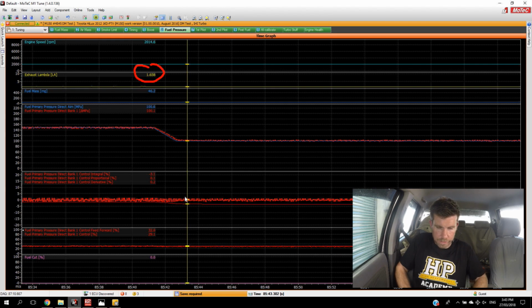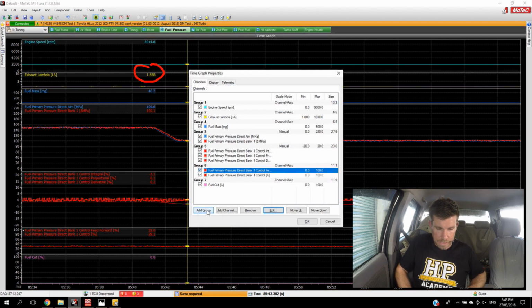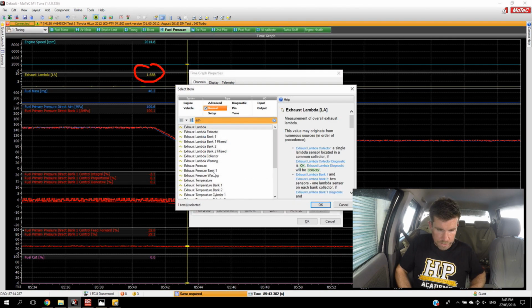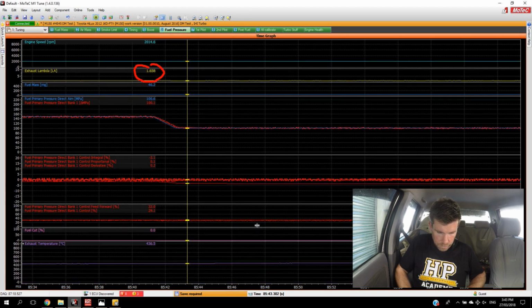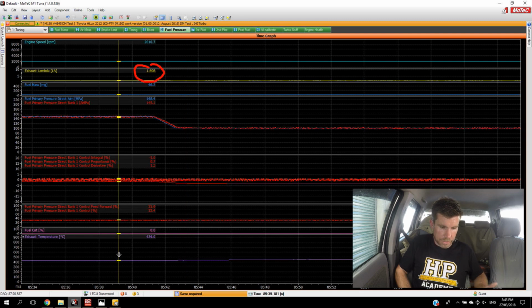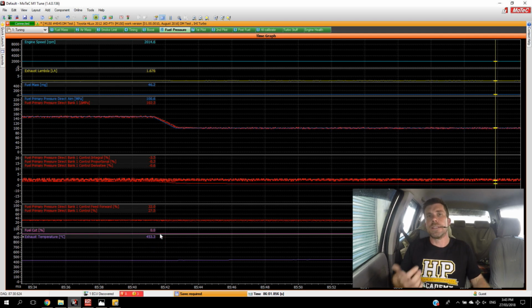And then we've of course seen our exhaust gas temperature. Let's just put that in here as a parameter, just so we can see the effect of that. Prior to making that change, we're sitting at 430 degrees, and after making that change, it does obviously take some time to change, so we're sitting at 450 degrees. So you can see there is a lot of intricacy in the aspects that will affect our exhaust gas temperature, and this is why it's really difficult.